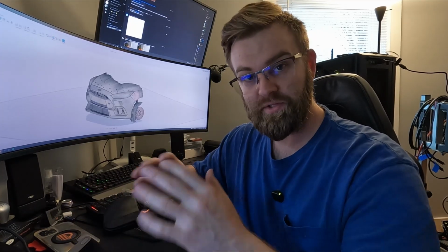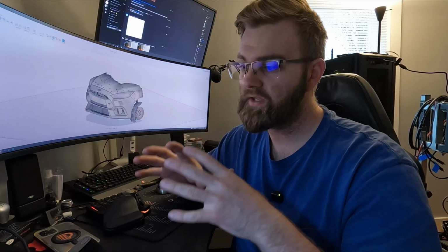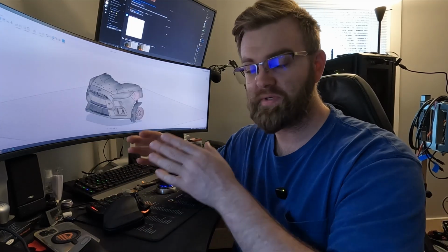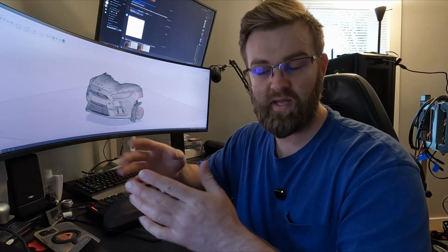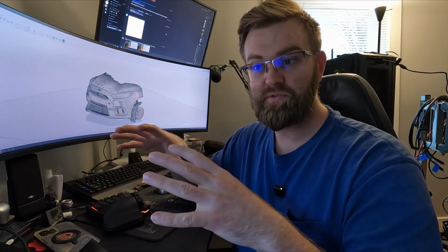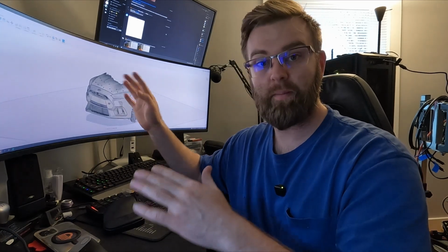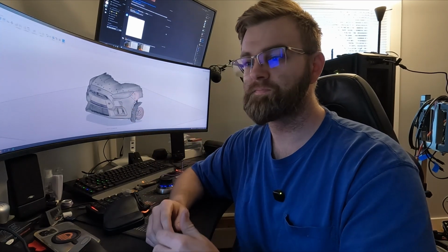So in the last video, I made a handful of scans. I think it was 5 in total. And in each of those scans, I made sure to scan enough overlapping data. So in between the different scans, with the bumper on, with the bumper off, the back side of the bumper, I had enough data points, 3 major data points, on each of those that overlapped. That way I could overlay them one on top of another within some margin.